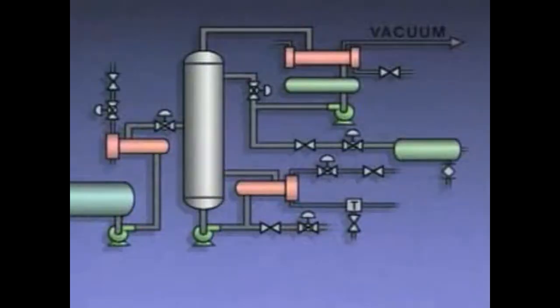Once column pressures and temperatures are close to specifications, overhead product and bottoms product can be taken off. Ordinarily, the product that reaches the desired purity first is the one that's taken off first. In this case, it's the overhead product. To prepare for the overhead product takeoff, an isolation valve on the takeoff line is opened.